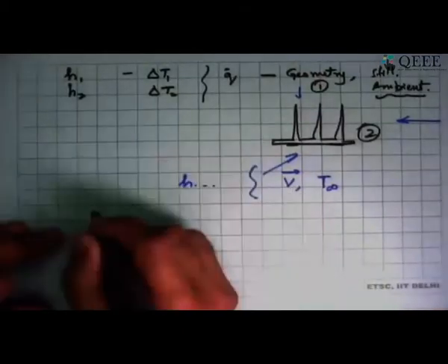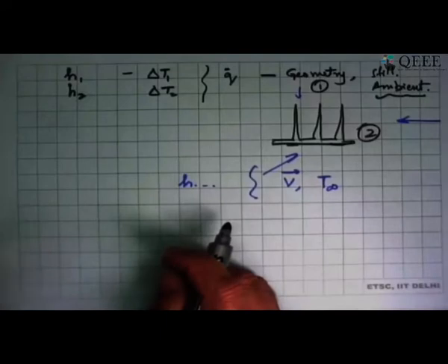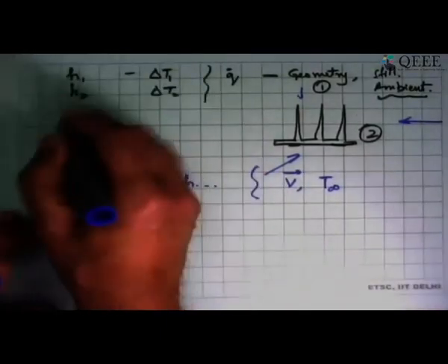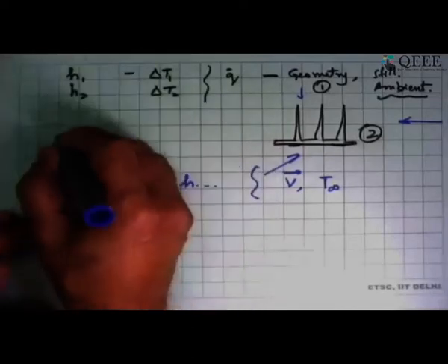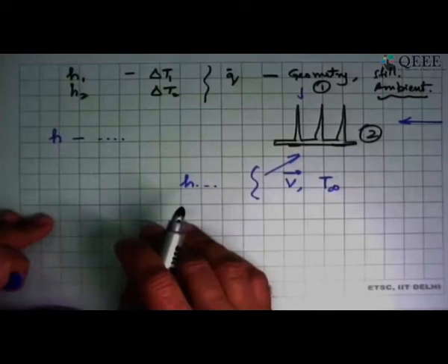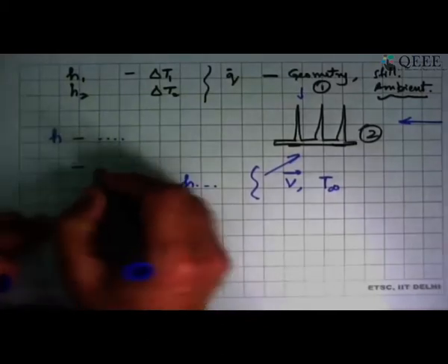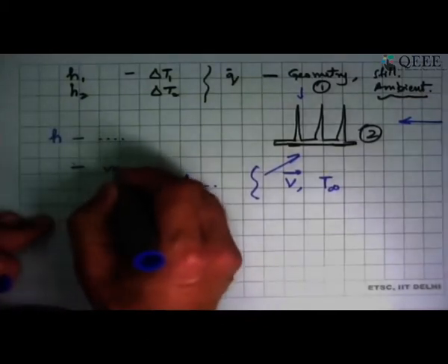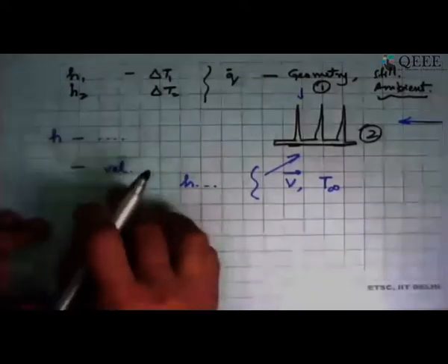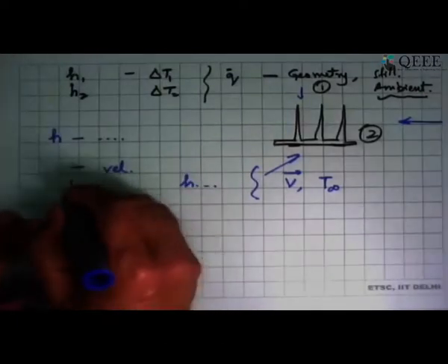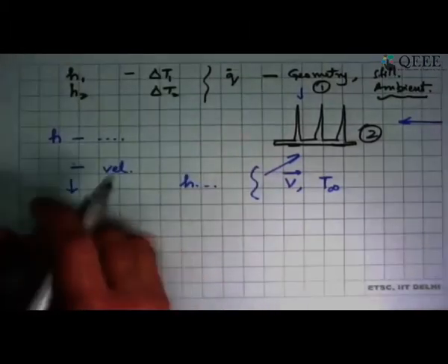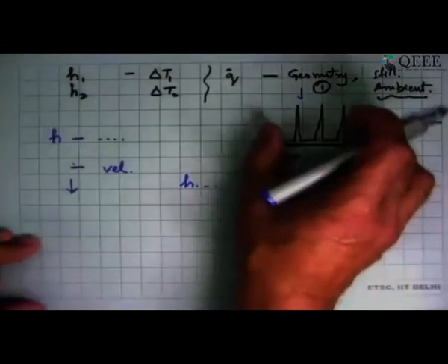So that's what we do. And to generalize this problem, what we do is that instead of solving it each and every time, we say that, okay, in this particular case, this is the relation between h and some of the other parameters. Or in the forced convection case, between h and velocity. So we say that we are able to explicitly get what this expression is, and then we will non-dimensionalize it, which we will do later on, how we do that. And from there, we get that for this particular type of a geometry, this is what happens.